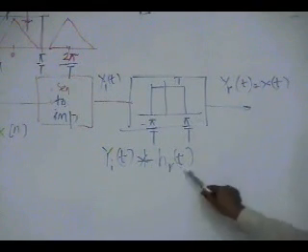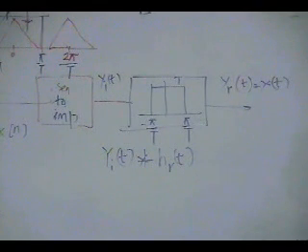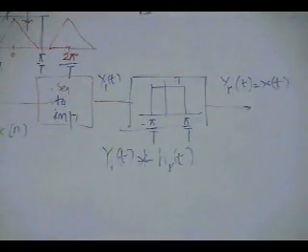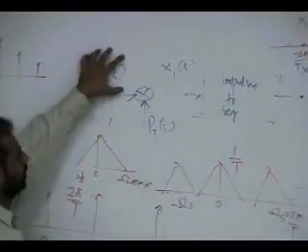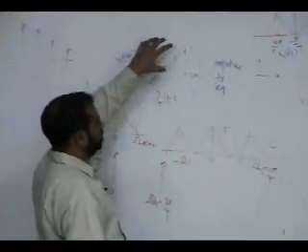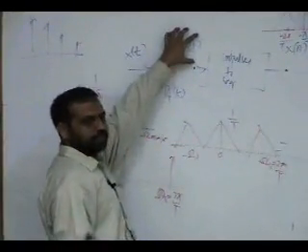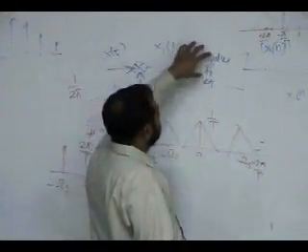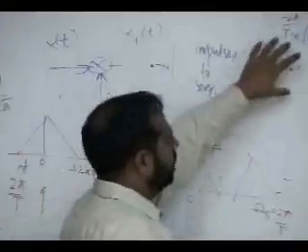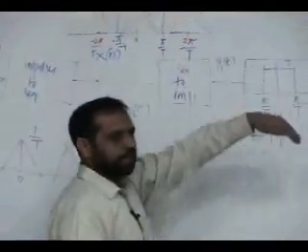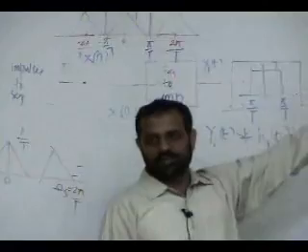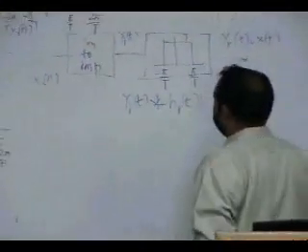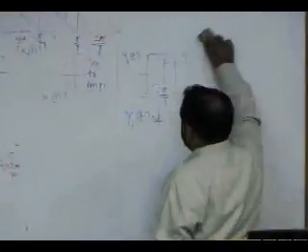So this is the reconstruction filter. So this is what we are doing: starting with a continuous signal, multiplying with the train of impulses, getting a train of impulses but in the shape of the signal, putting impulses to sequence, taking the time away, then sequence to impulses, putting the time back, then passing it through a low pass filter, and we get the signal back. And now we want to see what happens in time domain, how we get that back.